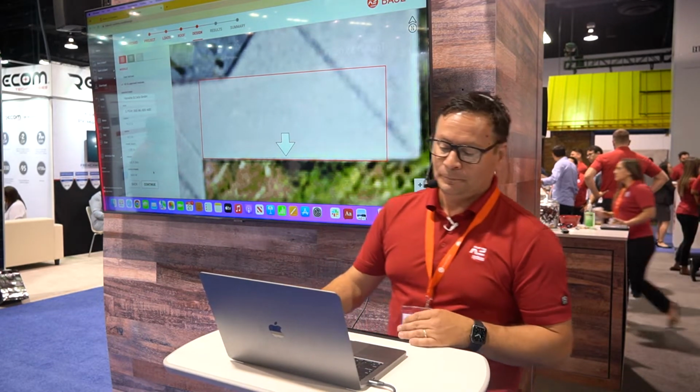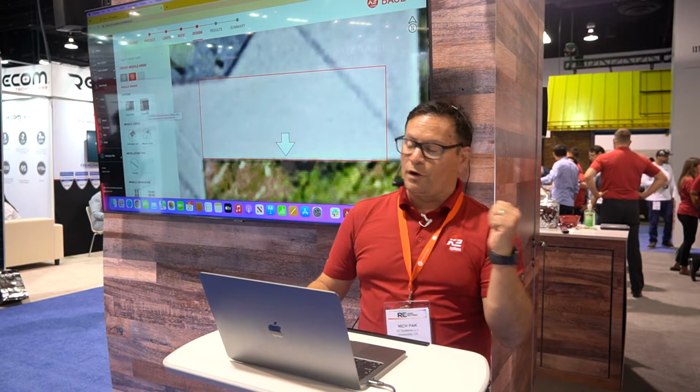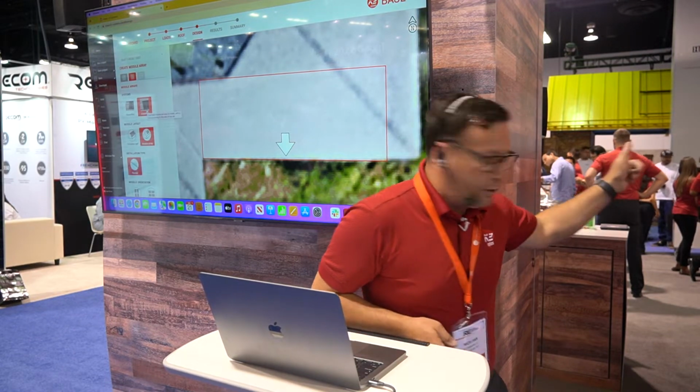It gives us the dimensions and weight of the actual module. This is very important dimensionally for GreenLancer to know exactly what size module you're using, so it flows over to them and they understand what they're looking at. After that, I'm going to click continue. It's going to ask me what system I would like to use, what type of racking. We're going to be using the Crossrail, the one that you guys saw up on the list, up on the comp roof right over there.